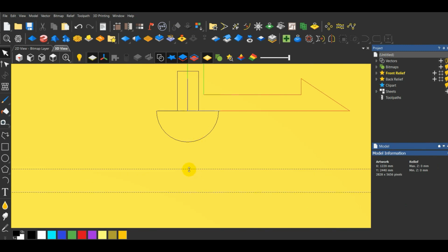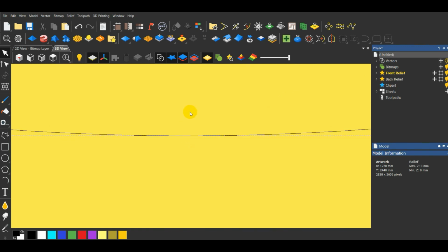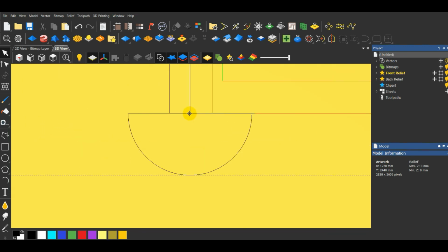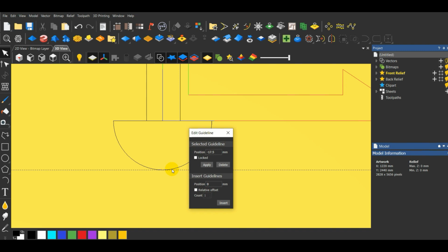So for 17 mm, let us consider a practical case where we are going to float it for an 18 mm thick, 8 by 4 feet sheet, that is standard size 1.22 meter by 2.44 meter, 18 mm thickness. The maximum cutting limit here is 17.5, but we can't do that much. We will limit it to up to 10 mm only. Let us do it for 10 mm cutting depth. Maximum I want is 10 mm. 8 mm will be the best for it.